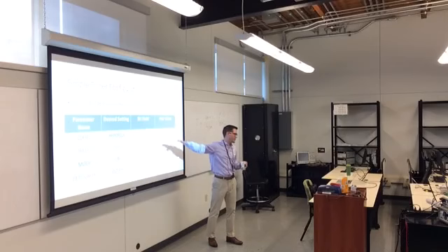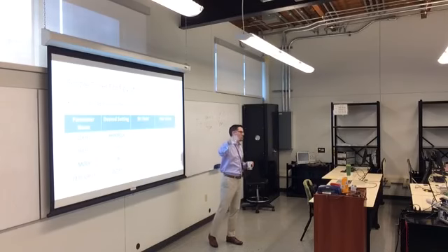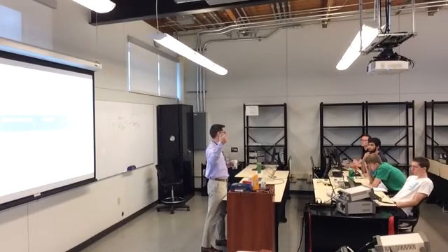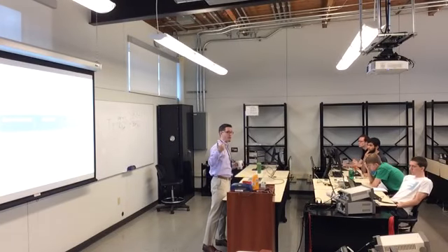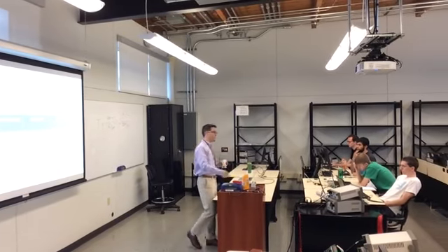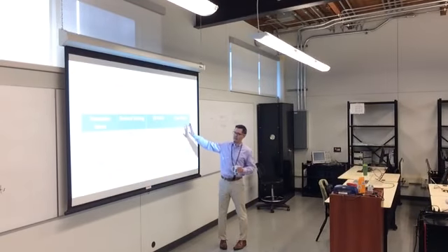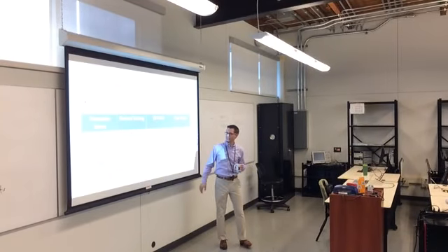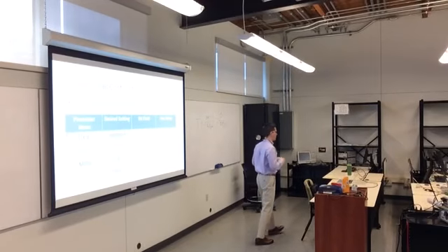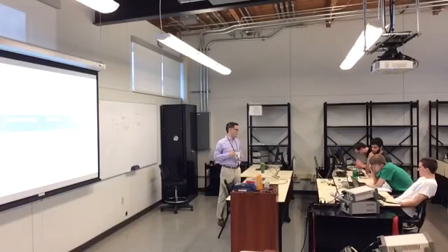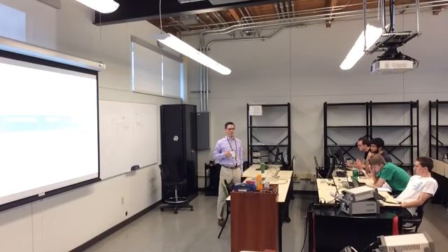It's the same thing you're doing with the GPIO. You've got to set the mode. Well, is the mode 0 through 3? Is it 4 through 7? What bits are the mode? What value do you want to set it to? So throughout the notes, you'll see this kind of table that lays out all this configuration. That's sort of the tedious part of the processors, is figuring out all the different configuration bits.